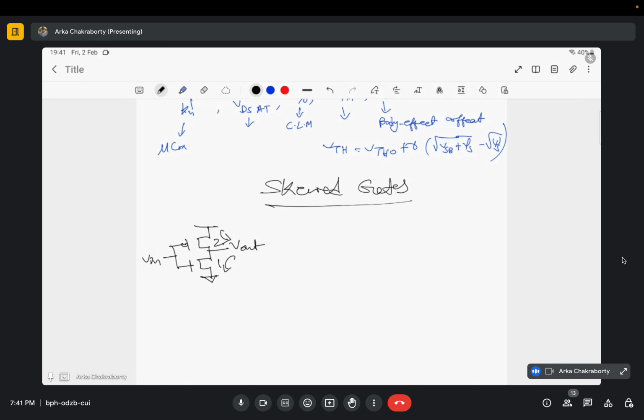I generally want the bit line to move from 0 to 1 at a much quicker rate than moving from high to low, 1 to 0. So I need a fast charging path, and I can afford a slower discharging path.